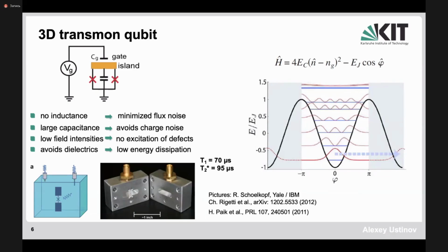However, here, basically the idea is to open up the capacitance, which was like this, sort of having pretty closely positioned metallic electrodes in 2 dimensions, and therefore quite a high amplitude of electric fields in the gap between the electrodes. Here you open up the electrodes, the capacitance drops down. So to come to the same value of capacitance, you need to increase the area of the metallic electrodes. You need to make the metallic electrodes larger.